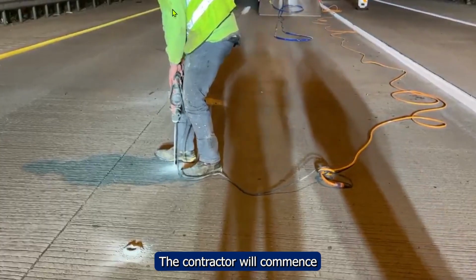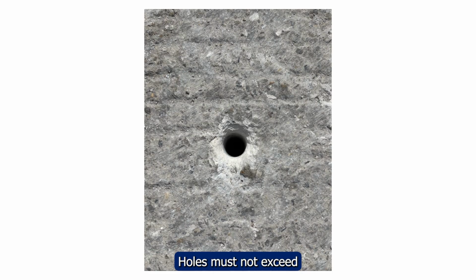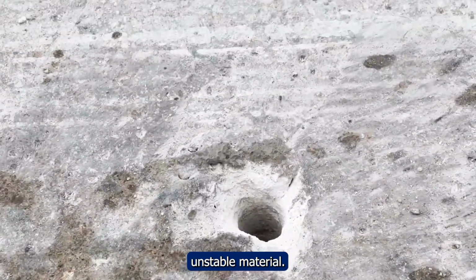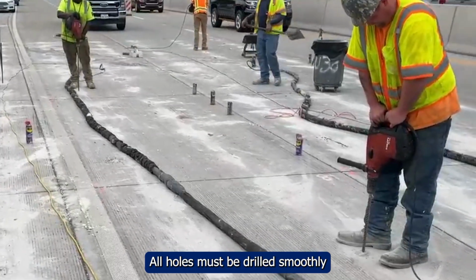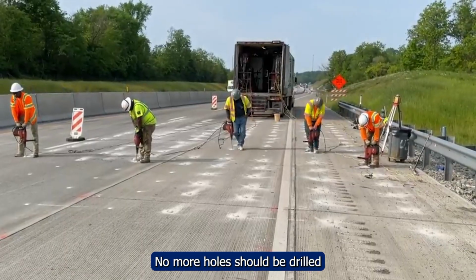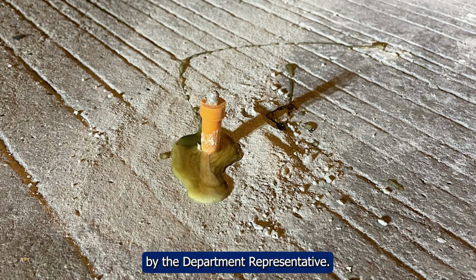The contractor will commence with drilling the injection holes into the designated concrete slabs. Holes must not exceed 5/8 inch in diameter and should be drilled to a depth sufficient to reach the underlying unstable material. All holes must be drilled smoothly and perpendicular to the pavement surface without breaking out the bottom of the slab. No more holes should be drilled during a single day than can be filled that same day, unless approved by the department representative.